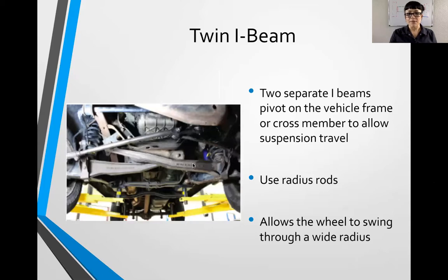So this one's a little bit different. You can see on each side on the inside, I've got, well, let's look here. I've got two arms. They almost look like long control arms, and they kind of are. It's preventing that in and out movement, but they're really, really long. On one side, I've got a connection to my frame, on the other side to where my wheel assembly is. And as the vehicle's wheel moves up, this whole arm pivots very much like a control arm, and it compresses the spring. Same on this side.